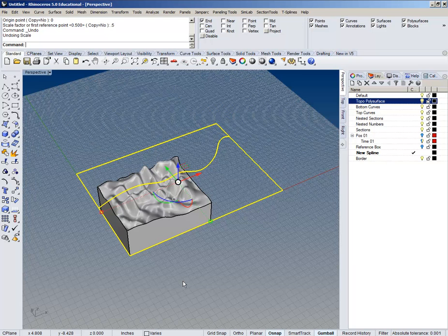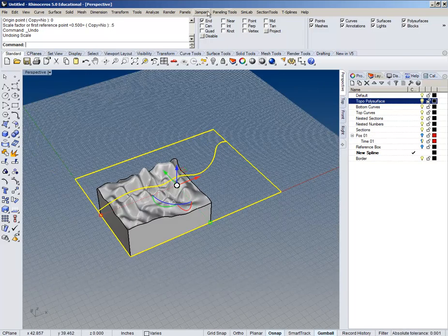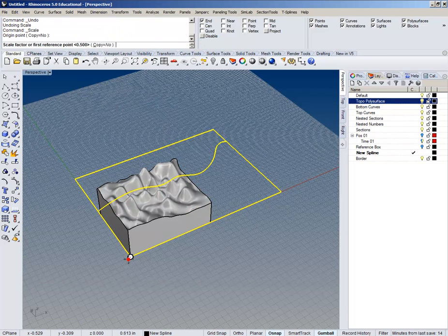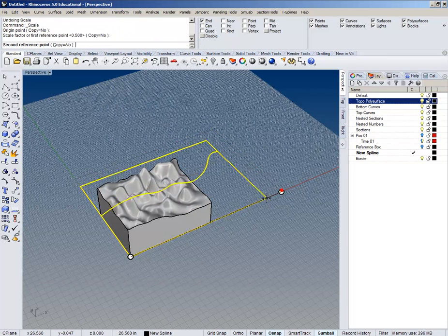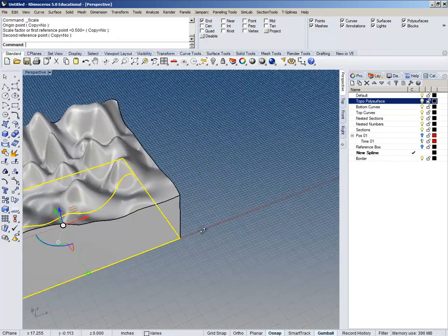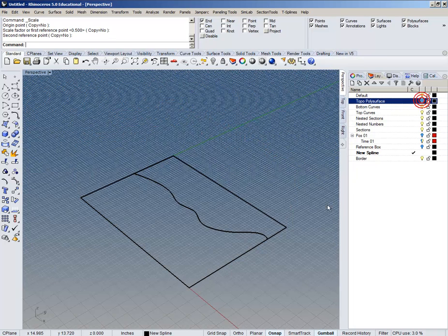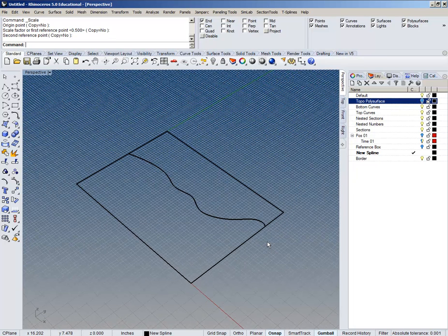you're going to want to scale it by using the two edges of the long axis, because the most important thing is that this spline touches both ends of this guy. So let's say you had to nudge yours a little bit to get it to work. Then you want to do transform and scale it from the whole size to your new size, and that'll address that issue. All right, so I'm going to take this off, make sure I haven't skipped any parts here.